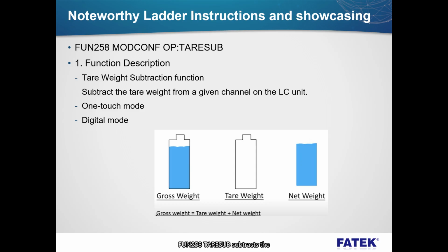Function 258 tare sub subtracts the tare weight from a given channel on the LC unit. One touch mode: regard the current weight as tare 1 and subtract it. Digital mode: subtract the designated tare weight value.